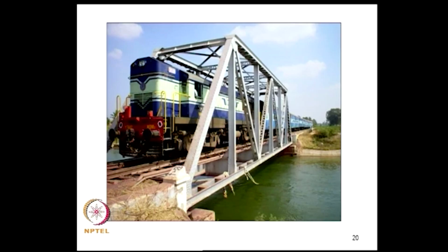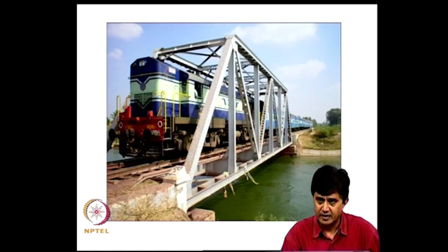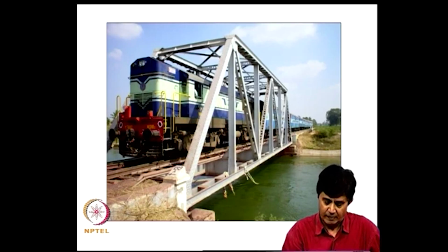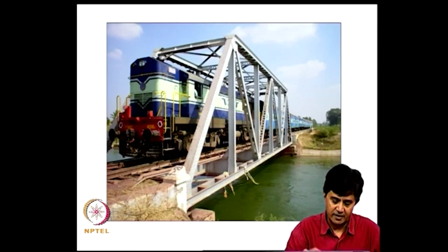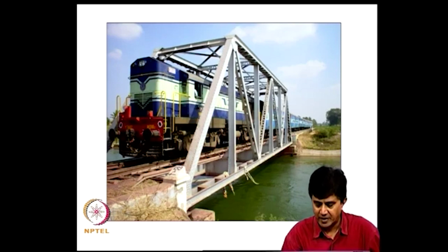The thing is, when do we need to do a vehicle structure interaction problem? That is a question that we can consider. Typically, if the mass of the moving vehicle is comparable to the mass of the supporting structure, and if the speed of the vehicle is high, and if the natural frequency of the vehicle and the bridge are comparable, there are various conditions under which one can expect that vehicle structure interactions would be important.